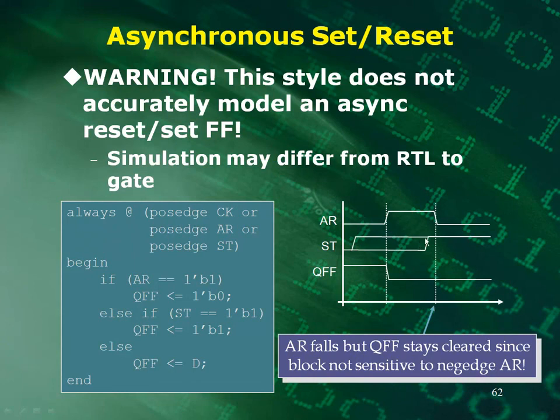Now, the asynchronous reset, according to this, is going to still keep it low because it has priority. But now we get to this point right here, when we release it, it goes back low, and our asynchronous set is still high. What's going to happen?